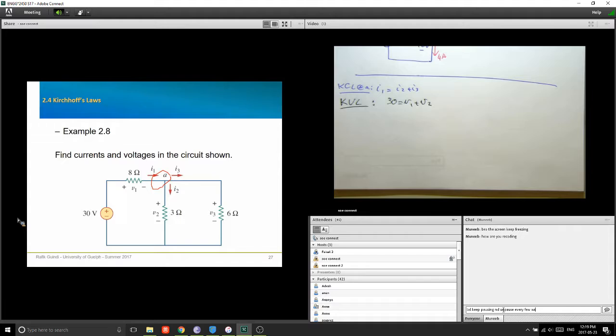The voltage across them is going to be the same. So V2 and V3 should be the same, right? Well, I'll tell you what, let's prove that. So why don't we write KVL around the second inner loop, the one on the right? If you were to write that, and you're starting at the bottom left corner as I do, and you're going from here, and you're going up like that, is that a voltage rise or a voltage drop? That's a voltage rise, equal V2.